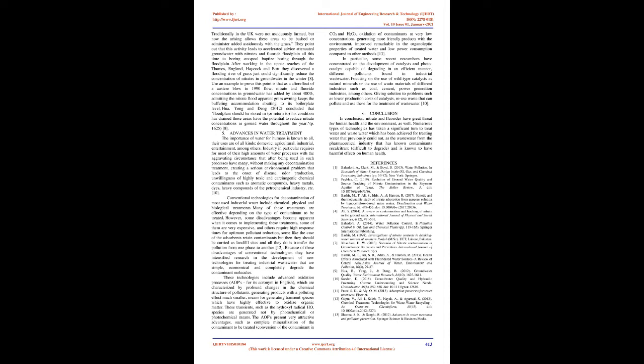Conventional technologies for decontamination of most used industrial water include chemical, physical and biological treatments. Many of these treatments are effective depending on the type of contaminant to be treated. However, some disadvantages become apparent when it comes to implementing these treatments. Some of them are very expensive, and others require long response times for optimum pollutant reduction. Some, like the case of the adsorbents, retain contaminants, but then they should be carried to landfill sites, and all they do is transfer the pollution from one phase to another.